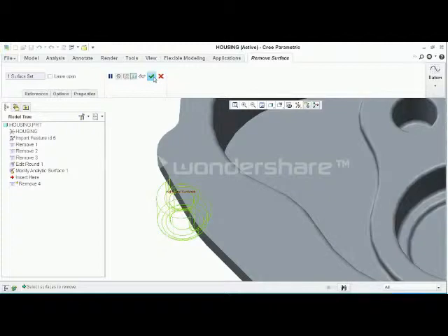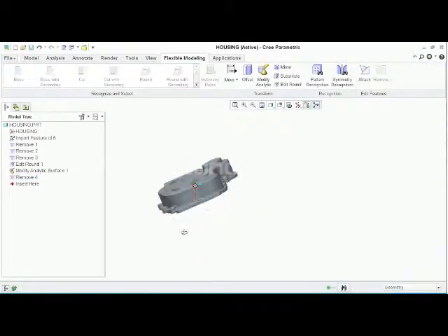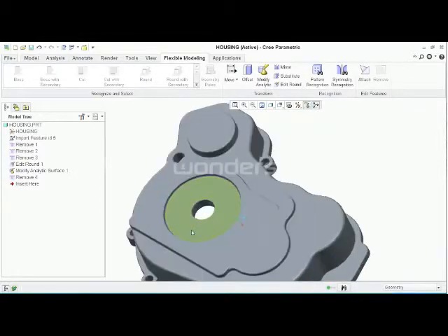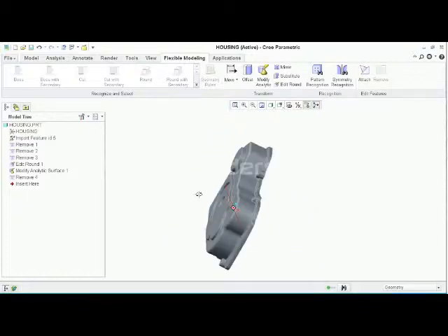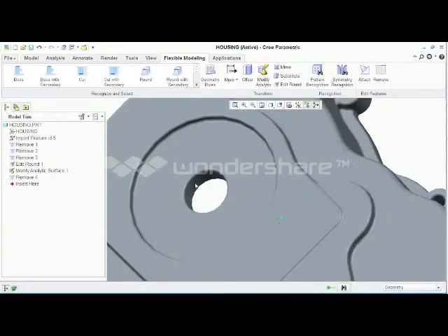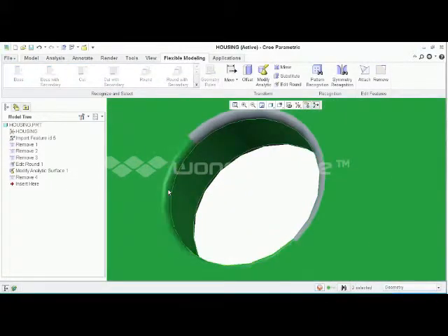All right. I want to do the same thing with this cut, this little kind of pocket, and this other cut on the other side. So I want to do the same thing with that to defeature it. Here I'm going to get some help from this cut option to recognize that, and then I'm also going to use the cut option to recognize this, and then I'm going to grab the remainder of the geometry. In this example, there's rounds here, and there's rounds on the outside.